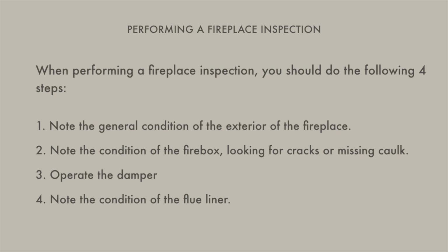When performing a fireplace inspection, you should do the following 4 steps. Note the general condition of the exterior of the fireplace. Note the condition of the firebox, looking for cracks or missing caulk. Operate the damper, and note the condition of the flue liner.